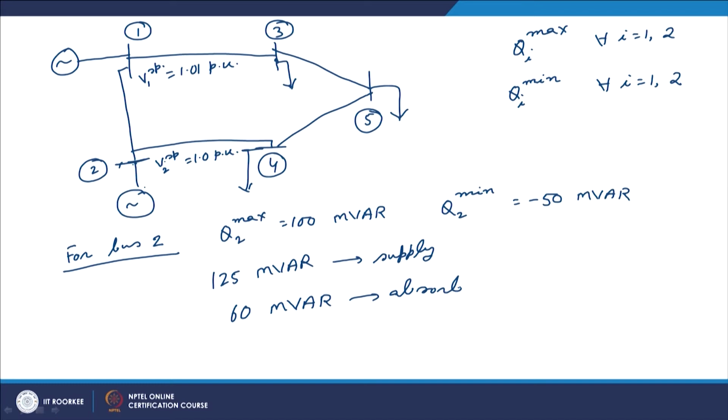So again, if the actual amount of reactive power absorbed by any generator is less than the amount to be absorbed by that generator ideally, then the terminal voltage of this generator will not be maintained at its set value, it would be maintained at a higher voltage.